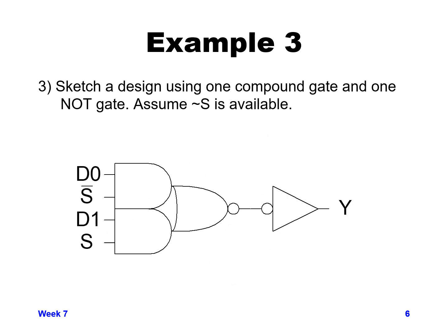So the design we would have is a compound gate that does the AND-OR function all in one gate. And again, it's always inverting, because a single compound CMOS gate will come out as an inverting function.